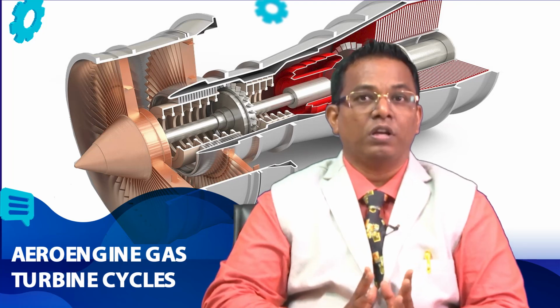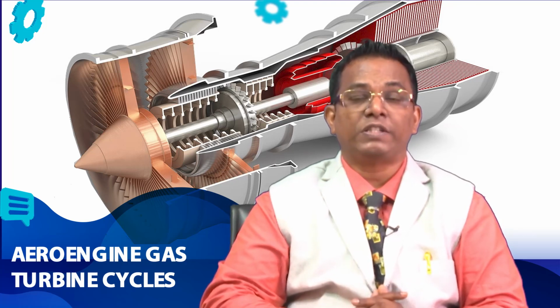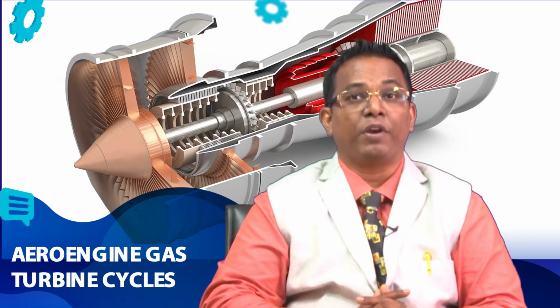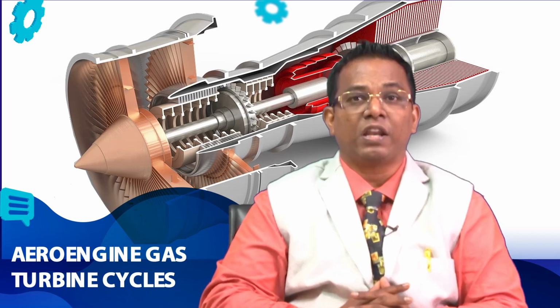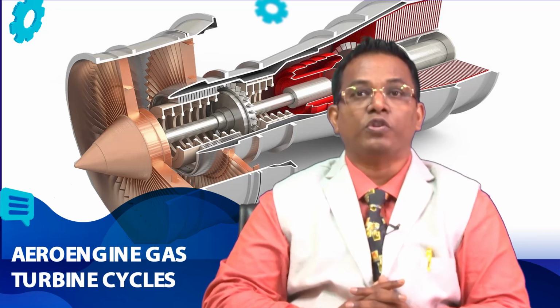Try to vary the performance parameters and plot how they change with different pressure ratios, different turbine entry temperature values, different mass flow rate values, afterburner values, and flying Mach number values. That will give you a great idea for detailed understanding. We are slowly moving towards the realistic condition, and we are trying to move towards a detailed understanding of the turbojet engine.